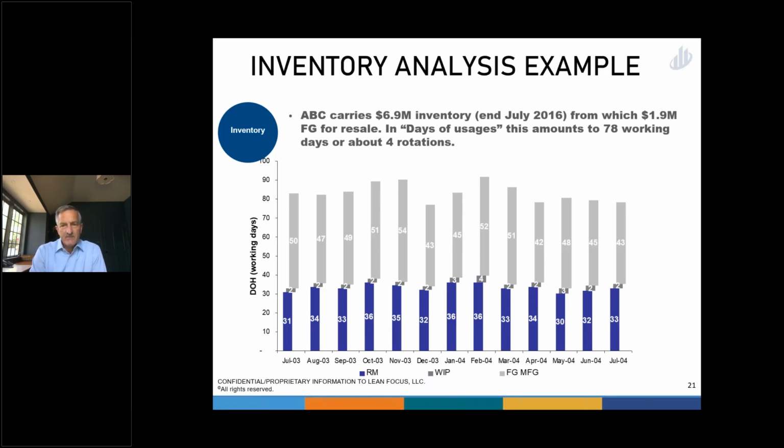And this analysis set up the importance of setup time reduction so they could run smaller lot sizes. So with some work on that, and also we installed a pull system to pull product through their manufacturing plant and actually reach back into the supply chain to pull materials into the manufacturing process.